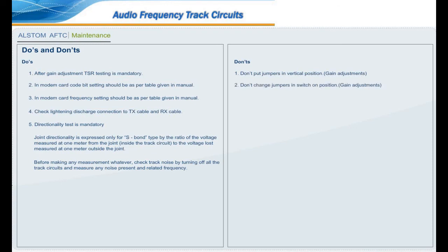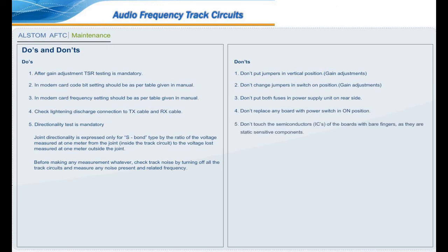Don't change jumpers in switch on position. Don't put both fuses in power supply unit on rear side. Don't replace any board with power switch in on position. Don't touch the semiconductor ICs of the board with bare fingers as they are static sensitive components.